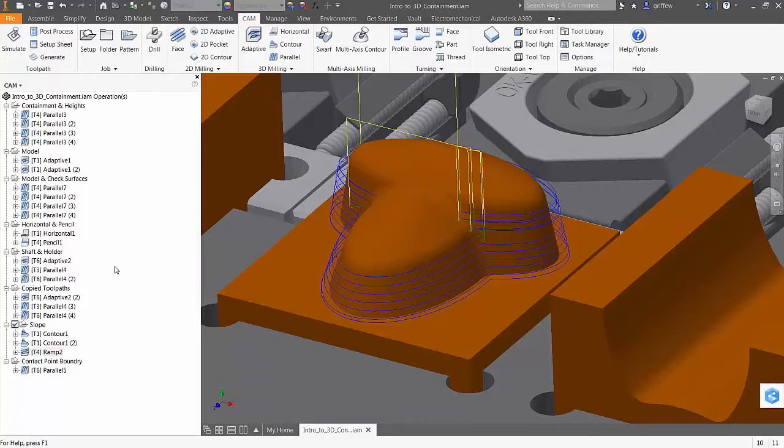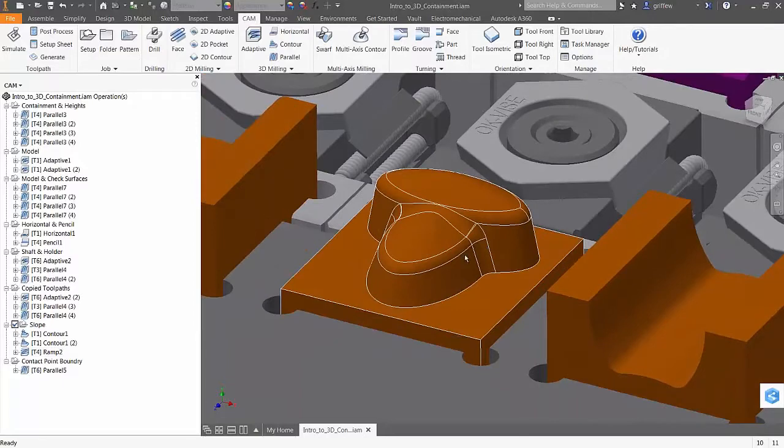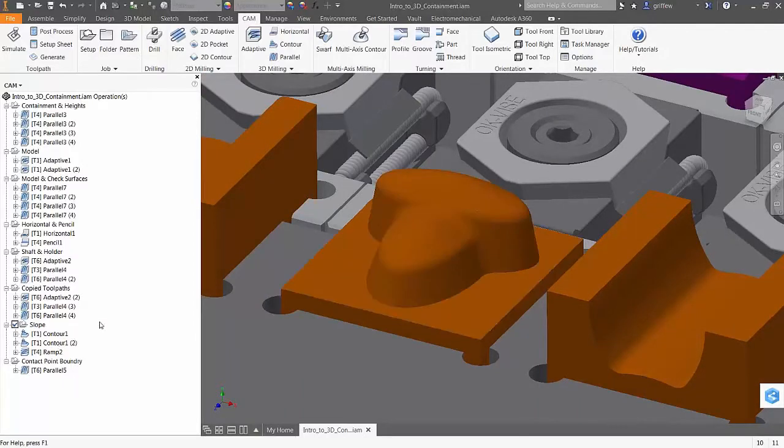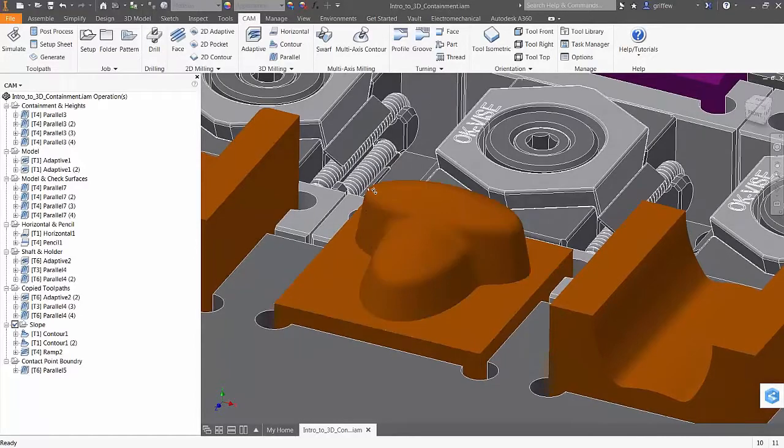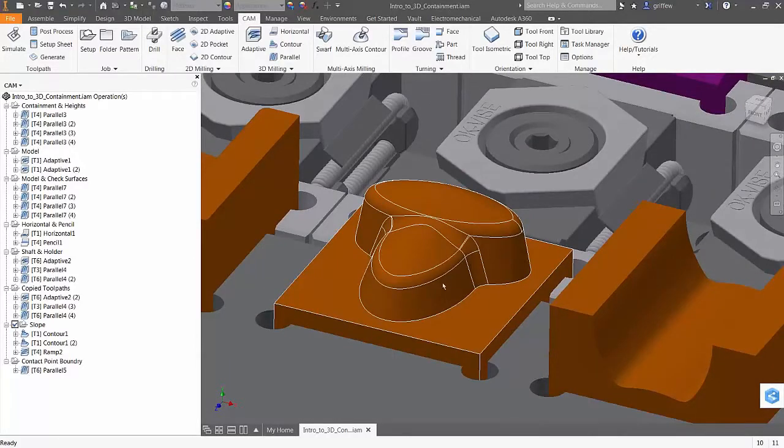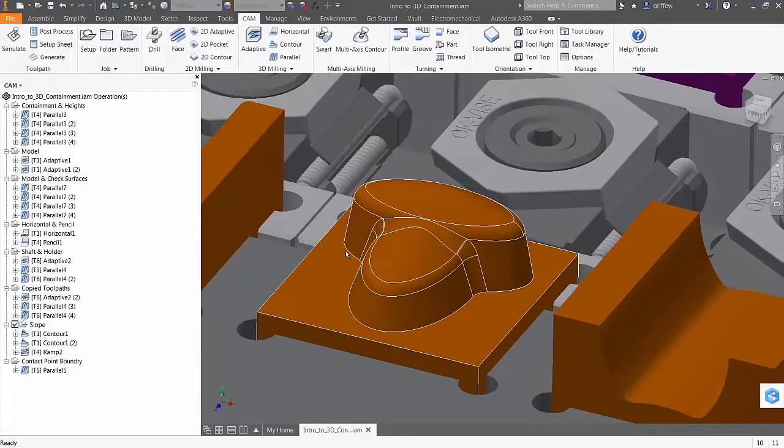Looks like it says when I use the ramp with the same settings, it generates 3 to 4 times more lines of code. Why is that? That's a good question, Ben. Because we're getting also Z moves in there too. So as you're using a contour, it's only looking at your X and Y coming out, moving down in Z and X and Y. So when you're using the ramp, you're getting all three vertices. In other words, you're using the X, Y, and Z simultaneously.